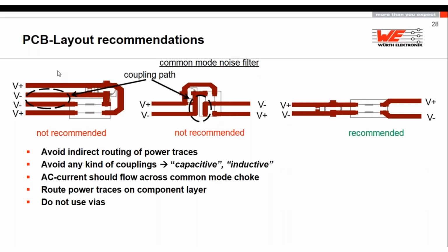I saw on the schematic, he placed the components the right way. But then I asked, let me see the PCB. Can you send me a PCB so that I can make my own measurement? As soon as I had the PCB on my desk, I saw what this guy had done. You have the noisy area on this pad. You try to filter it, you put a common mode choke, but after the common mode choke, in the filtered area, you couple back the noise.